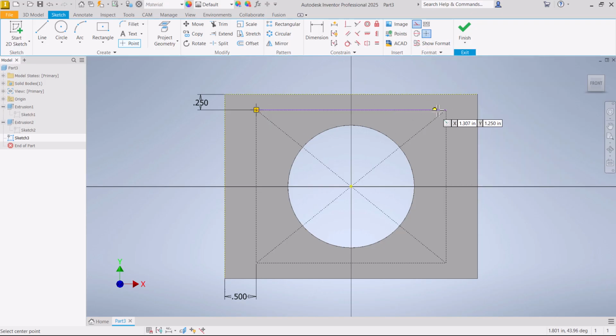That gives us a center point, which is what the hole feature will look for to create centers. And now as I go along and click, let's say I missed that one. So as I click, if I hit that point, I get my coincident constraint. This one, I wanted it down here on that corner and I missed. I can either drag and drop it. Now it is constrained to that point. Hit undo just to show again I can use the coincident constraint to apply the constraint there as well. Either way works. Either way is fine.